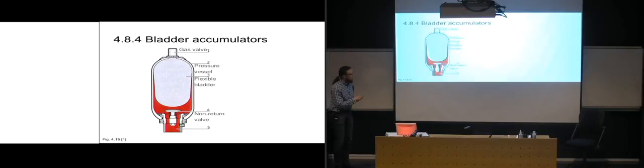So that one is there to protect the tip of the bladder so that it's not going to get any damage from the edges there. So it's usually, at the top here, hollowed out so that the tip of the bladder fits down into the hollowed out part of the poppet valve. And by the time the bladder has pushed the poppet valve all the way down, it has a tight seal along the edges here before the bladder expands over them, so that it's not going to get any damage from it. And then, of course, we have the fluid port in the end here, and all of this area allows for fluid to pass through it.